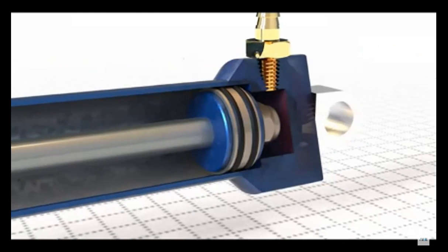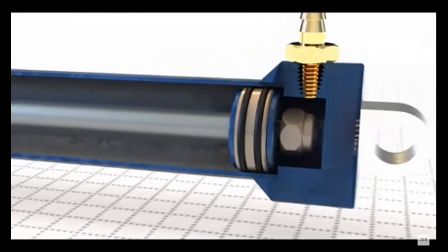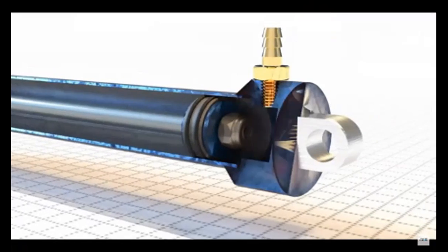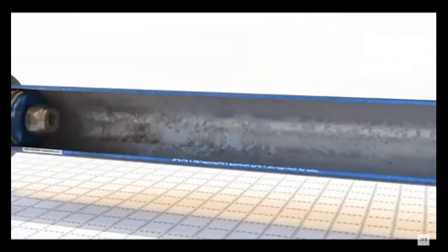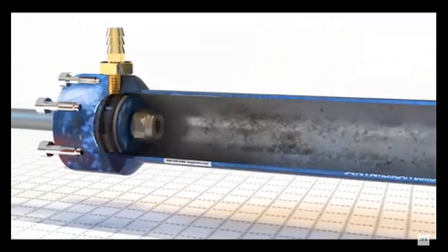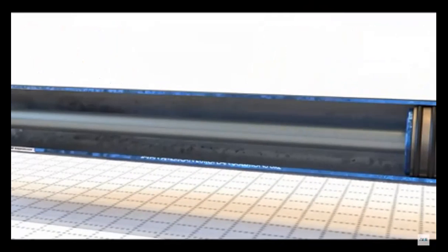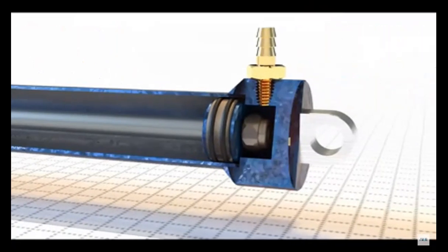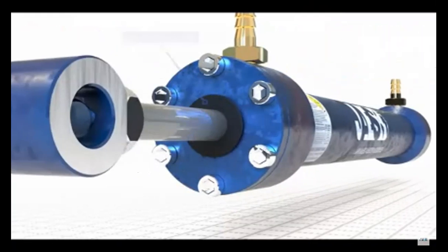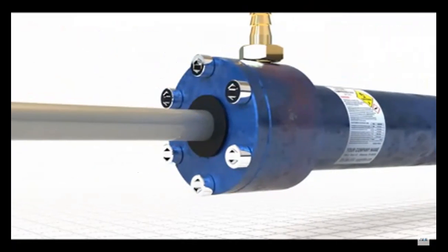A set of circular sealing rings are used at the interface of metals. The seals used between the surfaces of metals in relative motion are dynamic seals, and those acting between two surfaces at rest with respect to each other are static seals. A piston seal acts as a pressure barrier between two chambers separated by a piston. The wiper seal is used to wipe dirt from the rod while entering through the head and prevent contamination of the oil.